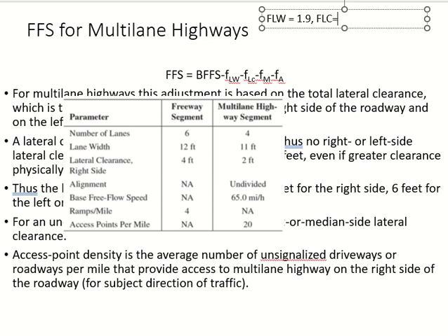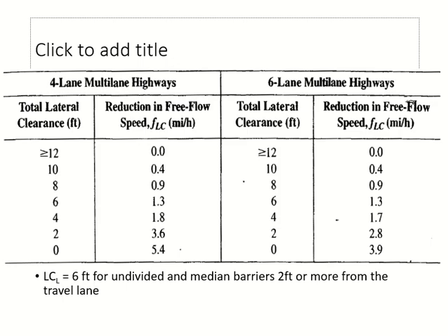FLC, factor for lateral clearance. How much is the lateral clearance here? 2 feet. But 2 feet is where? Right side. Which lateral clearance are they asking for here? Total. I have only the right side.